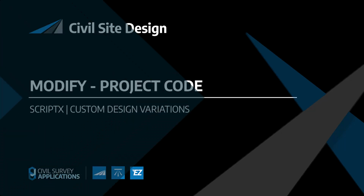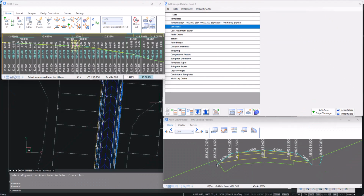In a design, it may be desired to pick a code in your cross-section that's not the batter and project that code to a surface. So if we have a think about this table drain, maybe what we want to do is to intersect that table drain code with a terrain.